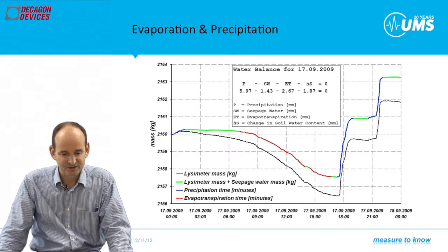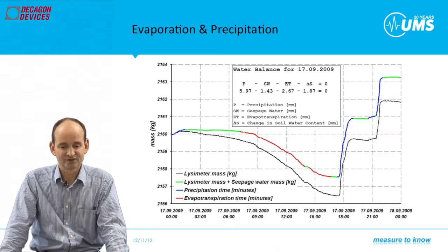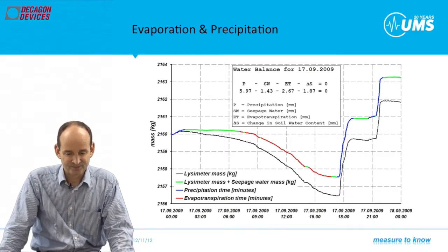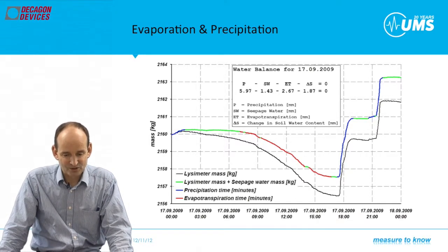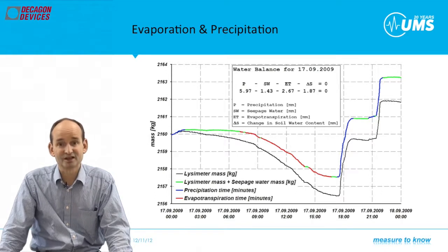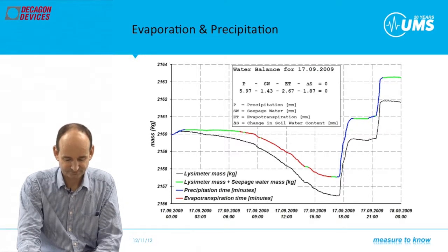On the other hand, rain does not start in hourly measure intervals, but rain starts in a minute and ends as fast. So the time interval for the raw data should be 10 seconds to generate a 1 minute average interval for data processing. Right now, we set up a group of lysimeter experts to work on an algorithm for rain and evapotranspiration out of the lysimeter weight data.